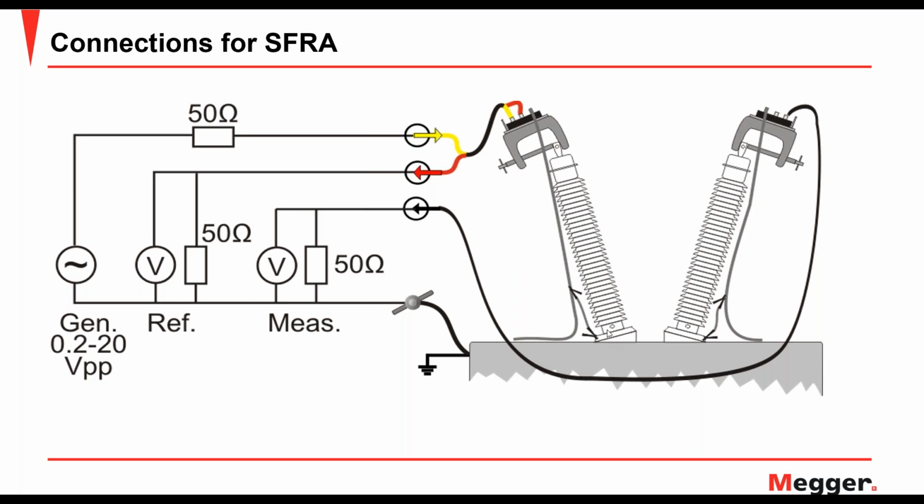This is done by using grounding braids instead of wires. So grounding braids, typically with a width of 2 centimeters, are dropped down and grounded at the nearest point, which is typically the bushing flange. You may not see any effects when you're testing on low voltage windings, but when we test on high voltage windings, with those high voltage bushings being really long, the grounding leads will be longer, and that can affect your measurements. We'll talk more about all of that in the future slides.